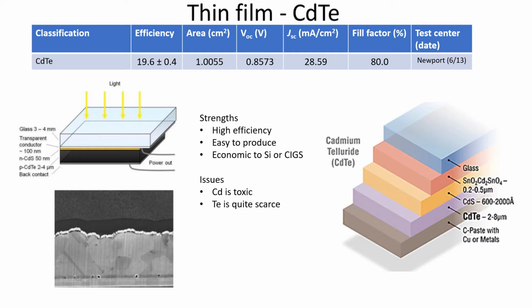The cadmium telluride solar cell has a similar sandwich structure as the CIGS solar cell structure. In the cadmium telluride solar cell, one electrode is made from a layer of carbon paste infused with copper, another layer from tin oxide or cadmium stannate, that is Cd2SnO4. The semiconductor in this structure is cadmium telluride. This cadmium telluride along with cadmium sulfide creates the N-type and P-type layers required to form a p-n junction for the PV cell to function.